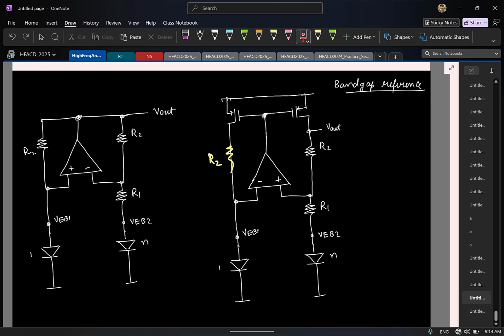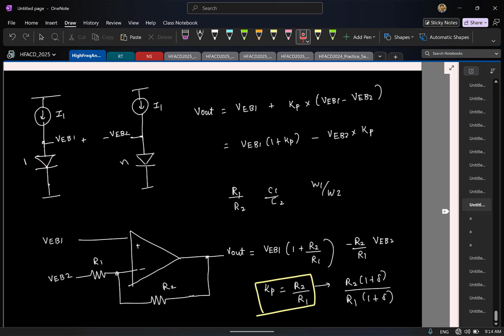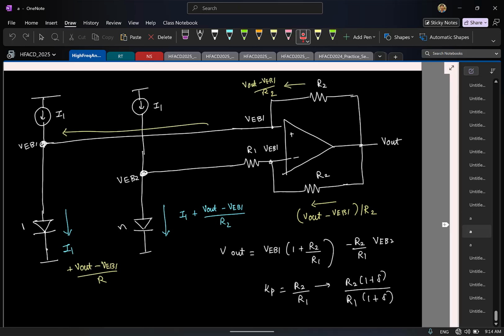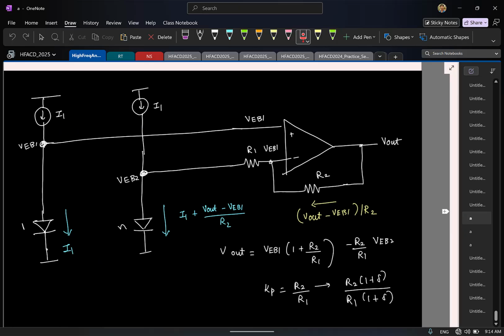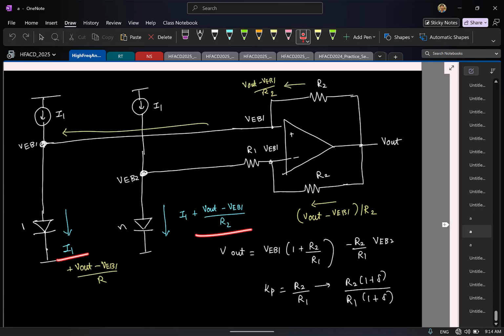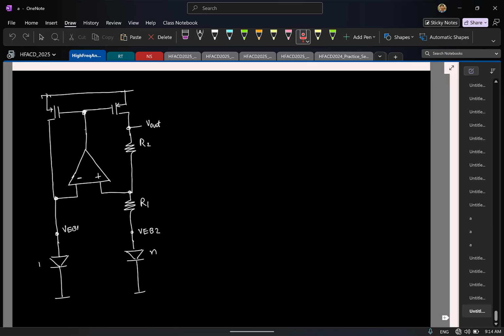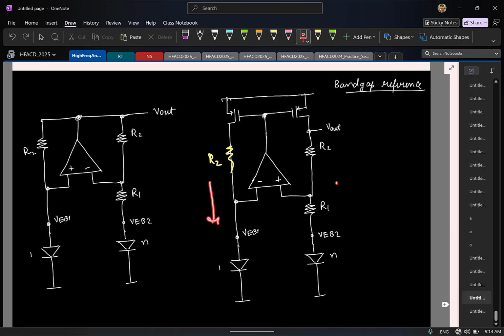First of all, why was this resistor added? Remember that when I had the first structure, something like this, the currents in both branches were unequal. So I added the resistor here to make sure the currents on both sides are equal, right? Now in this structure, again my goal is to make sure the same currents are flowing. I have a current source pumping in a constant current. So even if I use R2 or I don't use R2, it's fine, because now we have a very good current source making sure the current is constant. Even if we have it, it won't make a difference.